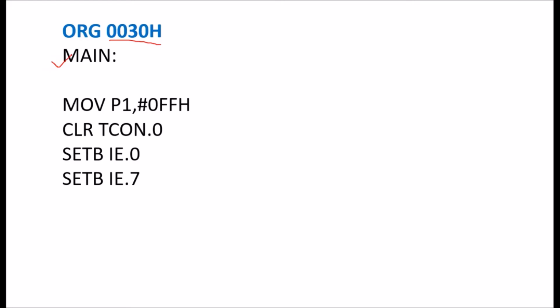So at address 0030H, this address is considered here because it comes after the end of all interrupt service routine addresses. You can use any address, such as 0100H. Here we'll write the main label, and the main program will be written here.